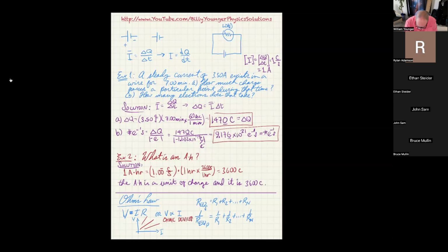For instance, there are Zener diodes that go like this and that, and light bulbs that go like this, and various other things. In those cases, we say the resistance is variable over current and voltage. It's just a matter of checking the slope on the spec sheet to figure out what the resistance is at a given setting.